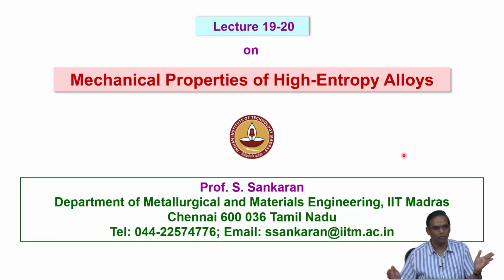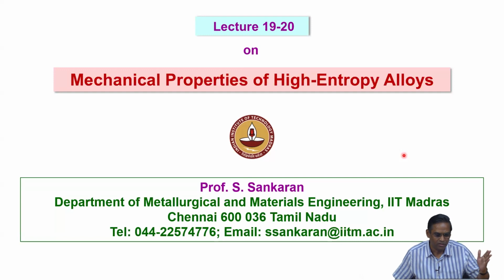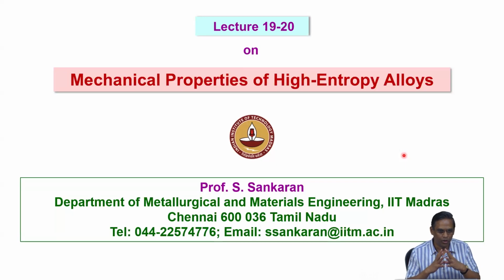And then we also know the popularly known stacking fault, right? When you look at the broad classification of materials, you have materials which during deformation exhibit either a wavy slip or a planar slip. This classification stems from the concept of stacking fault energy.